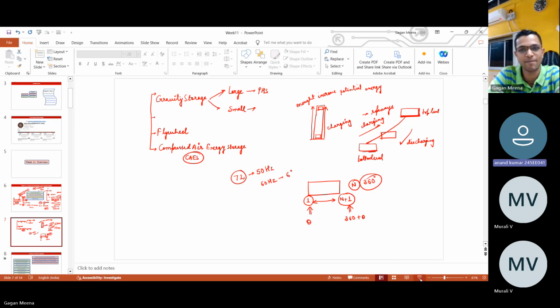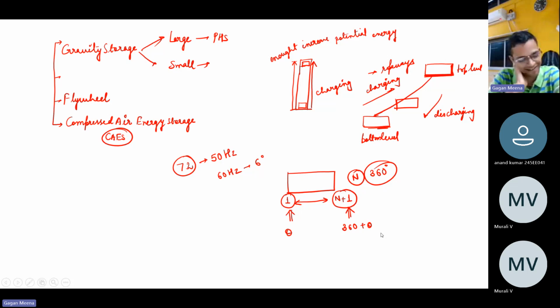Because in one of the questions, which is a numerical question, you may get a value which is quite large. There was one question asking what change in generation is required to restore the frequency or tie line flow to a particular value, and the required change was much more, I think 2 to 10 times the installed capacity. So that is not possible. Theoretically, it is possible.